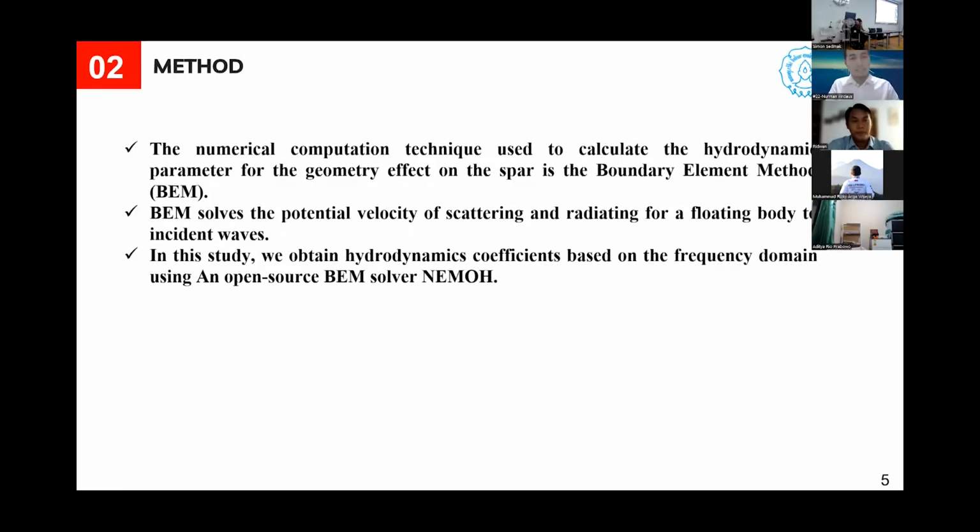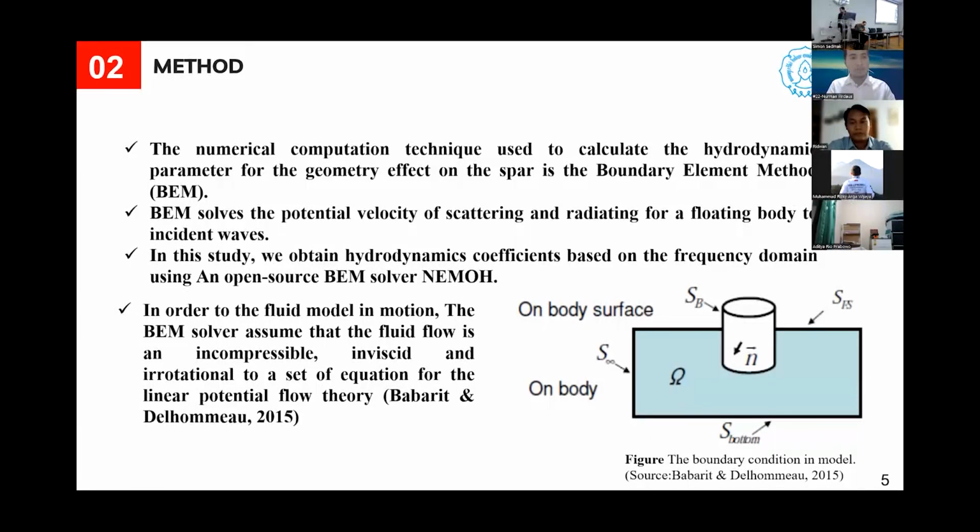In this present conference paper, we obtain hydrodynamic coefficients in the frequency domain using an open source BEM solver, NEMOH, from Nantes, France. In order to model the fluid in motion, the BEM solver assumes that the fluid flow is incompressible, inviscid, and irrotational, following a set of equations for linear potential flow theory. This figure shows the components of the boundary conditions in the numerical calculation.